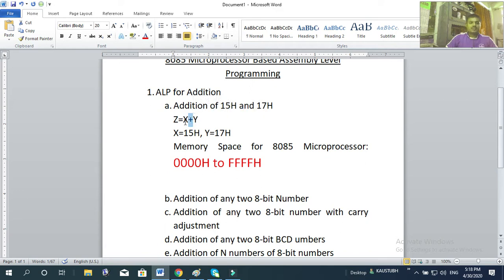And after that, as you know, before the execution, one of the operands is in the accumulator, and after the execution, the result is stored in the accumulator, always, for any addition instruction. Okay, so you may keep your results within the accumulator itself, or for further verification you can take it out from the accumulator, or copy it somewhere into a memory location. Okay. So let's start to write the programs.